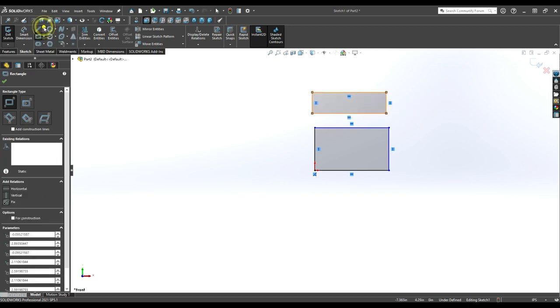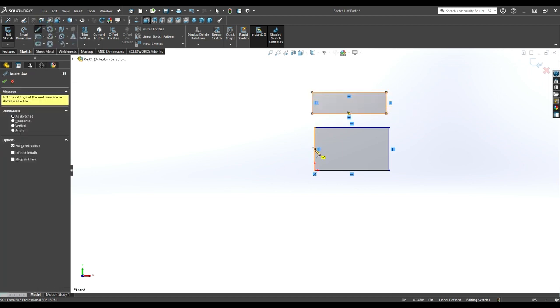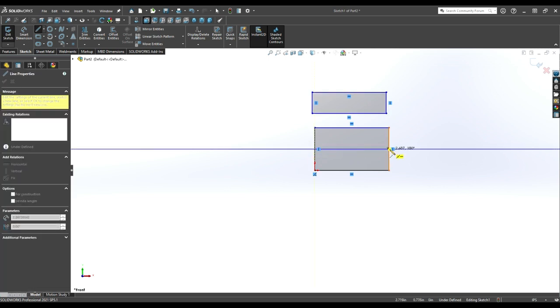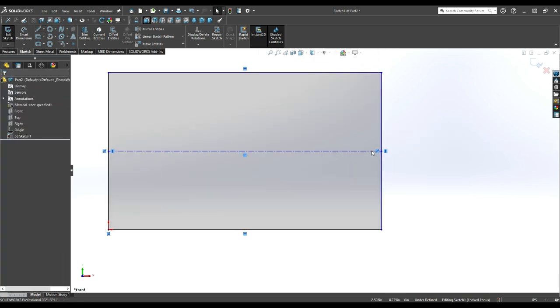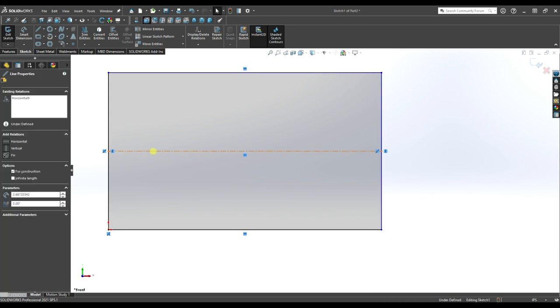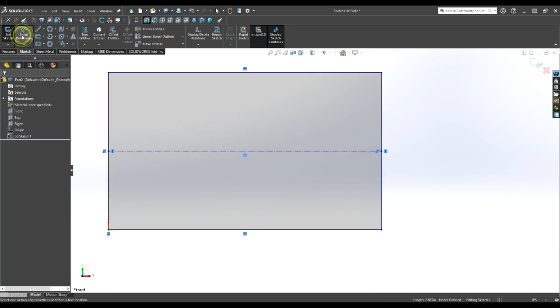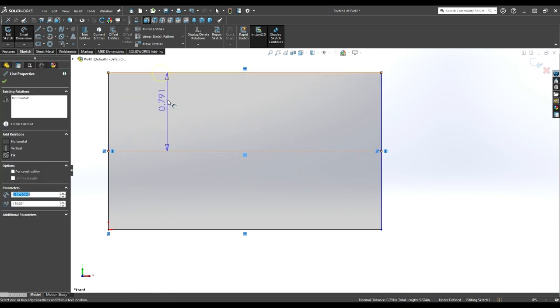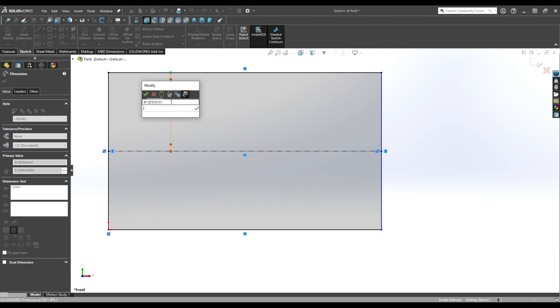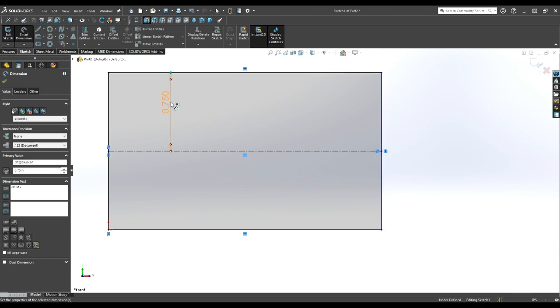Then you have different options for each feature. Say we just want to mark the center point. We can put a center line on there. You can use that as a reference to dimension things. I will make this 3/4 of an inch off of the center.